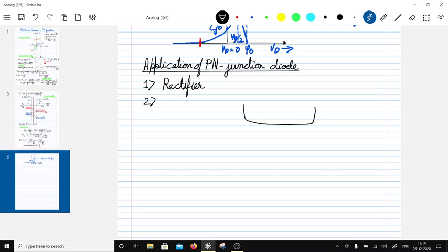The PMOS device is going to sit here in an N well, over the P minus substrate. This is going to be P plus, the channel is going to be P here, this is the gate, then source and drain. Then you can put in an N plus body terminal here. So this device sits in its well.